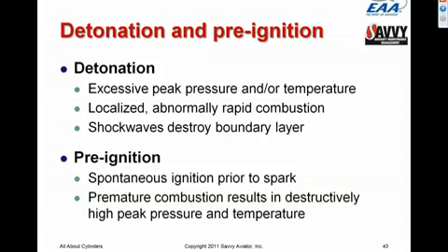I mean, when you think about it, it's really quite astonishing that we can create a combustion chamber that in large part is made of aluminum. The piston crown is aluminum, the cylinder head is aluminum, with a rather low melting point, and then create a 4,000 degree combustion event without melting the piston or the cylinder head. And the reason we can do that is because there's a boundary layer of relatively cool gas that protects the piston crown and the cylinder head from those high temperatures.